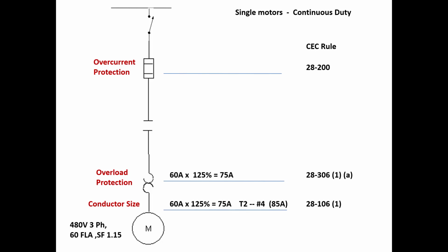Okay, so if you go to Table 29, I'm going under full voltage, resistor, reactor starting, across to time delay fuse, and getting 300%.